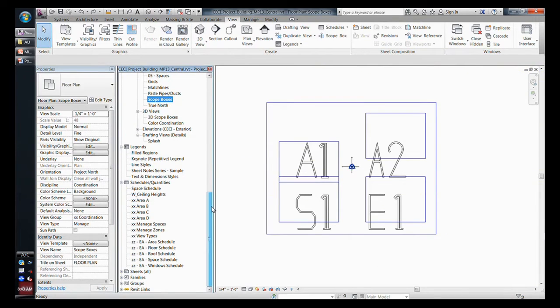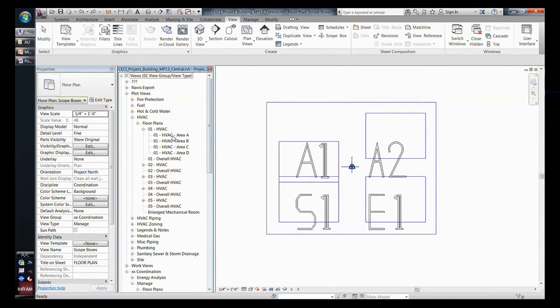And the way I managed to do it is, Project Browser does not sort areas, I should say dependent views, in a way that you can easily hold down Shift and delete them. There is always the main view that you might want to keep. You just want to delete the dependent views. So that became a challenge. How do I get rid of those area views when a project does not require those and I want to clean up my project setup process?